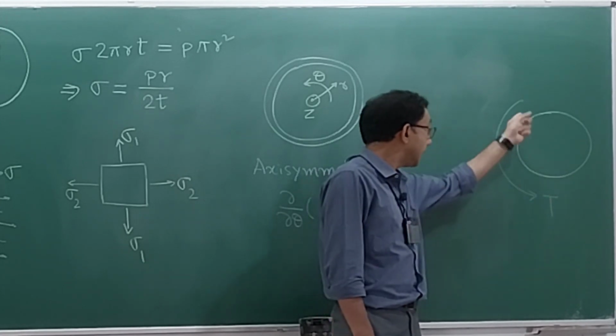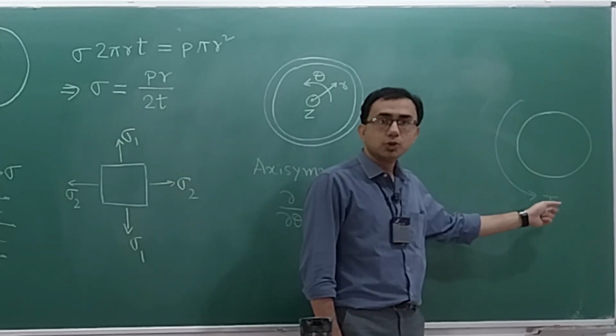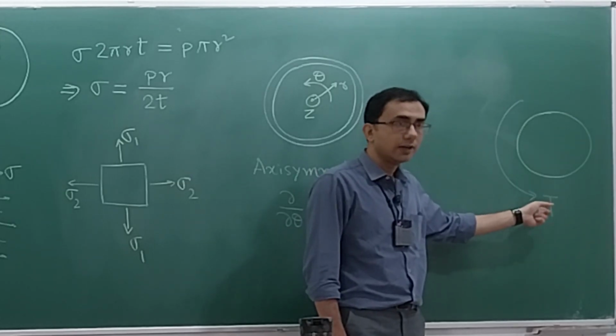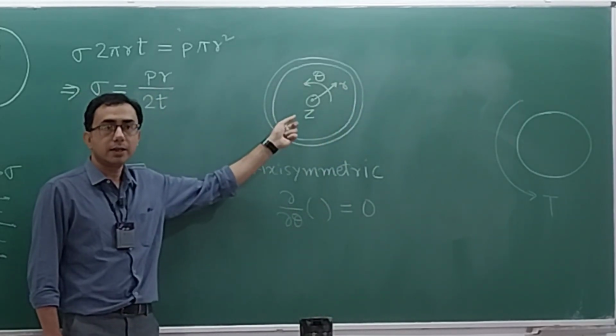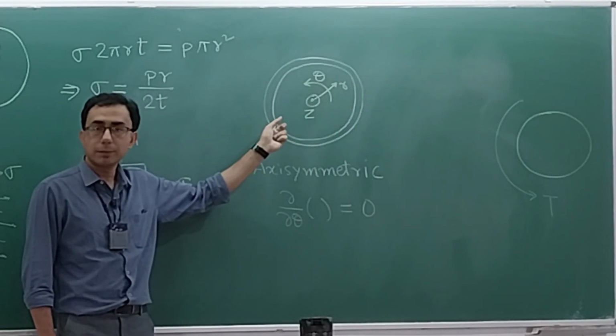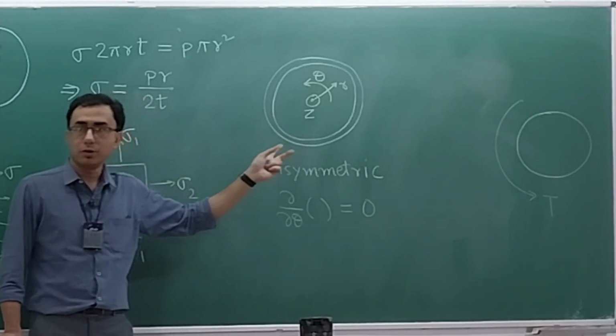But here, because you have a loading in this twisting direction, in the theta direction, you do have some deformation in the theta direction. But here we obviously do not have any deformation in the theta direction, because there is no load in the theta direction. Please be very careful about this.